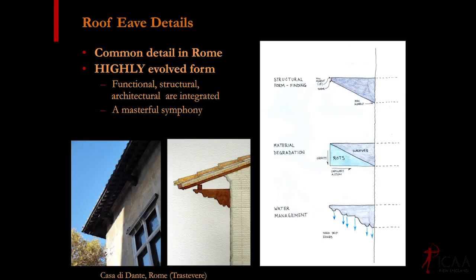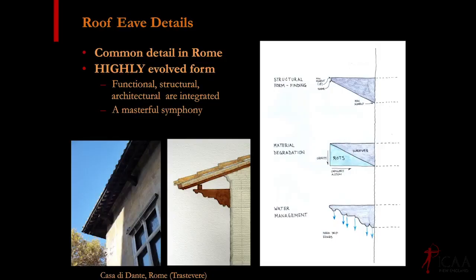So that's how they made pine work in this rainy, humid climate, untreated, unpainted, and never wrought: A, keep it so it almost never gets wet. It takes almost a pure horizontal rain to even get this wet. And then when it does get wet, you get that water off it very quickly. And by having it unpainted, I think it's an advantage in terms of the drying potential. It dries out really quickly, just like an untreated cedar shingle, particularly up at this height where the wind's really whipping past all these buildings. So that's how this has survived for all these years and done so well.